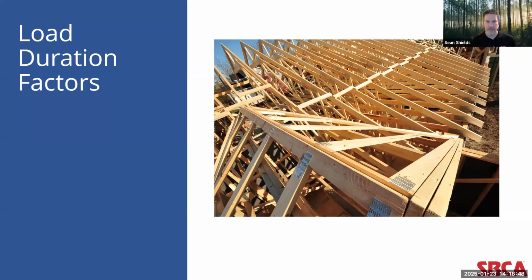But on a basic level, design loads are classified by how long they are expected to act over the life of the structure. So for example, an LDF of 10 years is considered normal loading. So the LDF is 1.0 and neither increases nor decreases allowable stress when designing a truss. But in contrast, a 2-month load duration is usually applied when considering snow loads, and that has an LDF of 1.15, which means that the wood in the truss can safely resist a 15% increase in its maximum allowable load, as long as the time under this load does not exceed 2 months.